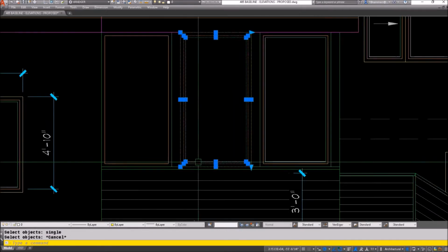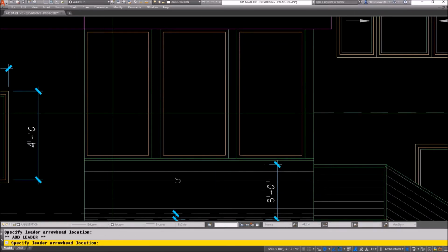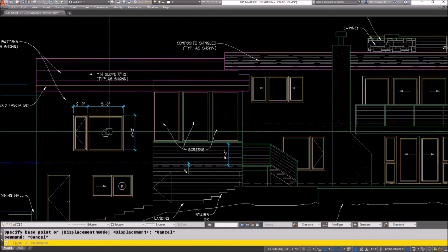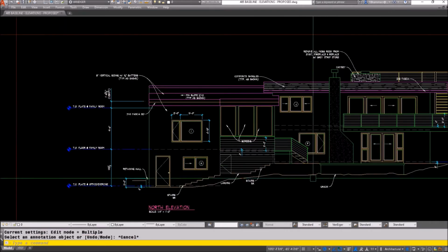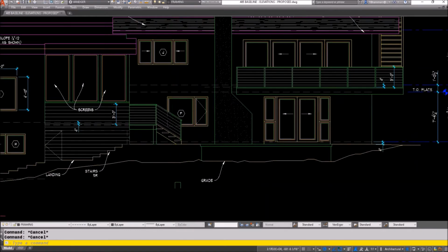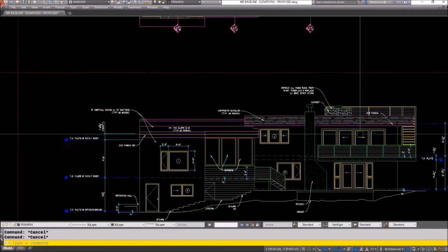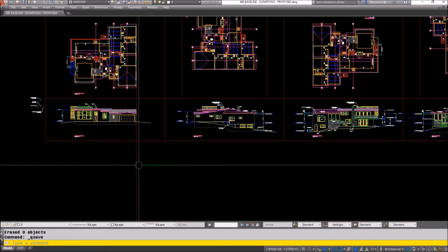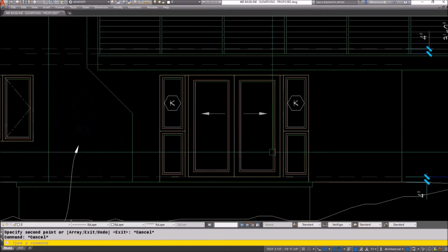Here's the screen thing I was talking about. So I took my window, I just exploded it, removed some of the mullion, called it screens, added vertex. That's another thing you can do with the control keys. You can add vertex to a multi-leader. You can add and subtract vertices and arrows from a multi-leader. This window was too tall, and that was stucco instead of stone. Point to the chimneys, make sure they're all labeled nice and clean and clear. This is window K.